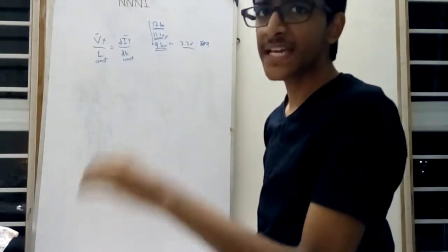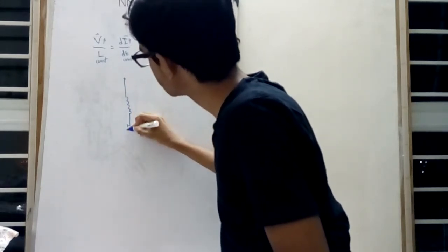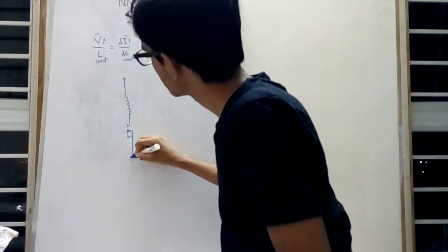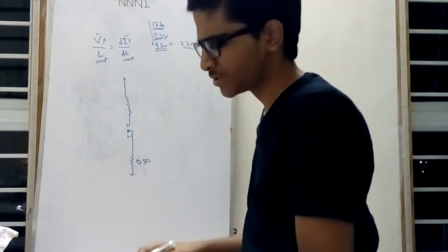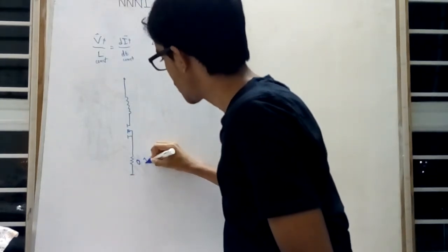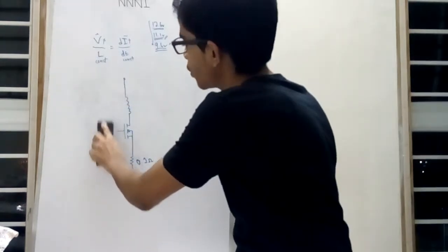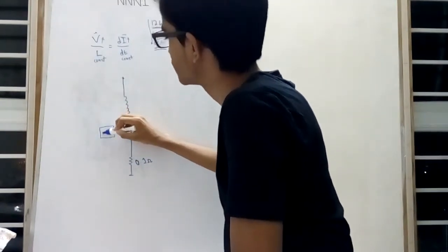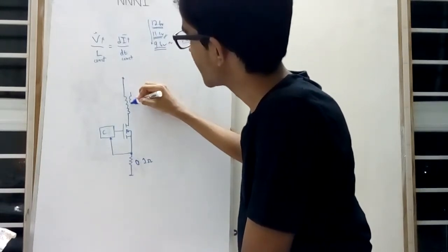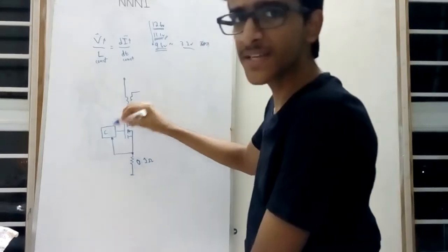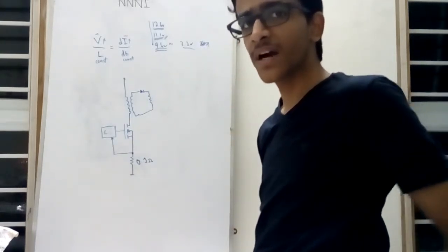Now, how do you solve this type of problem? The easiest and simplest method, which I will show you right now, involves a current shunt resistor of a very low value, 0.10 ohms, in series with the MOSFET and the primary winding. Oh god, why do I keep drawing off-ramps? And this is the controller. Let's keep it as C. And you have this input over here. This is the secondary winding. This could just be a simple op-amp circuit if you know how to wire that up. So this is basically the simplest current controlling circuit.